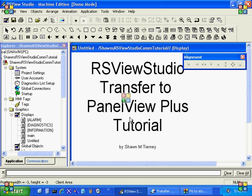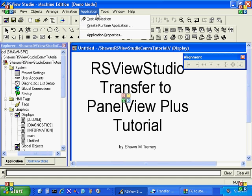Once you're finished designing your RSViewStudio Machine Edition application, you typically want to transfer it to your PanelView Plus. So in this case, the first step would be to create a runtime file that the RSView Machine Edition runtime on your PanelView Plus will be able to use. To do that, we're going to choose Application, Create Runtime Application.